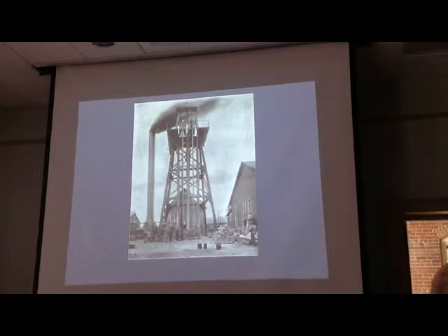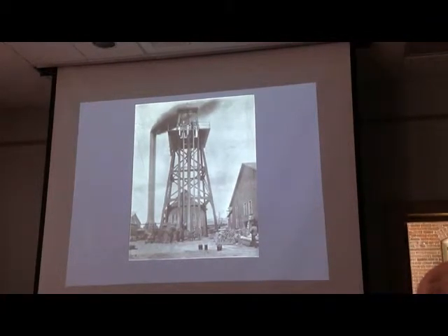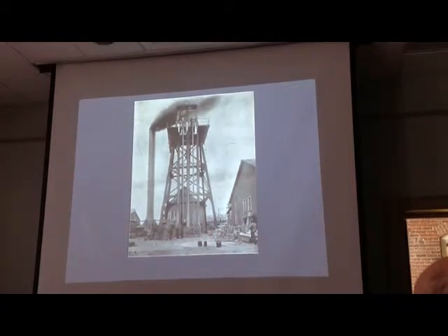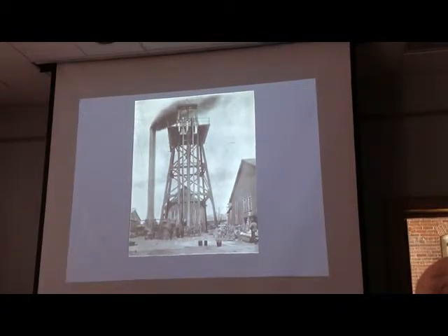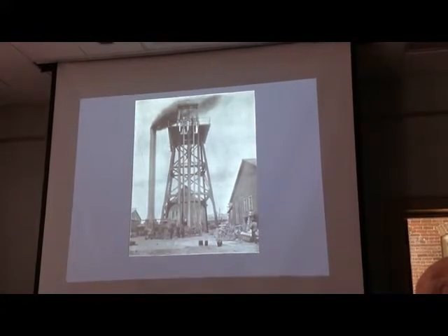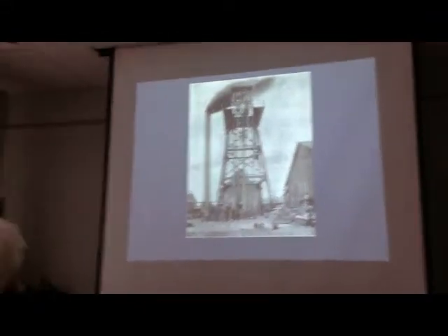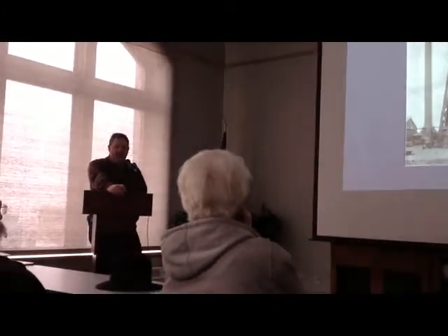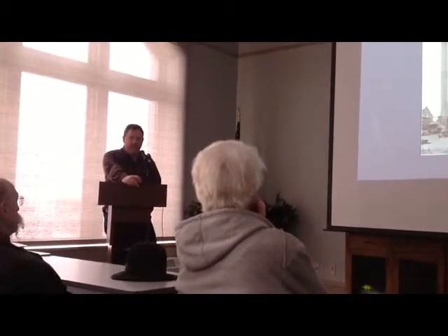There hadn't been very many steel head frames built. Eventually, the Anaconda was adapted for skips. It hoisted 8-ton skips. Now, the skip bins are below the collar of the shaft, so this is why the short head frame didn't make a difference on the Anaconda. The Anaconda, even when it had a shaft house, had a 40-foot level. And a 40-foot level, just to forestall a question, is roughly 40 feet under the collar, they drive it out of the mountain so that you could feed the railroad bins.